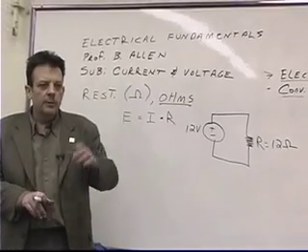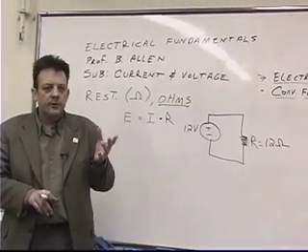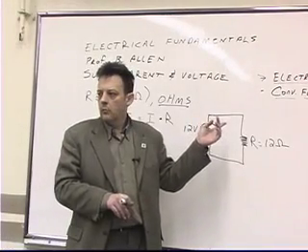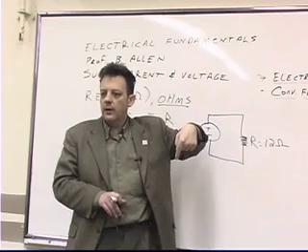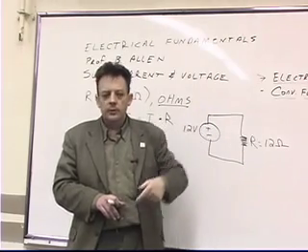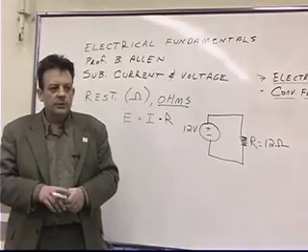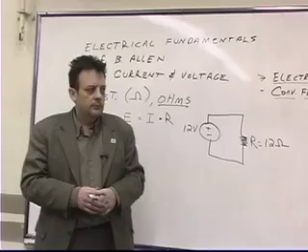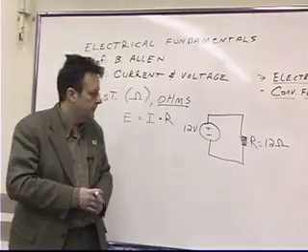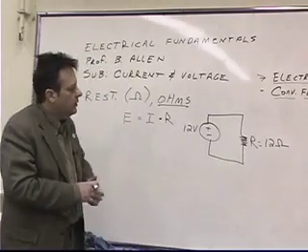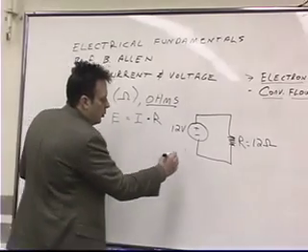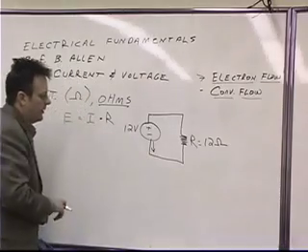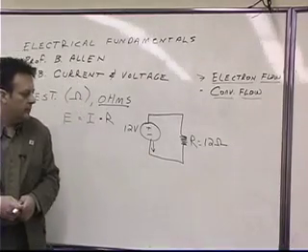With a little bit of math, all they have to say is, yeah, that's a negative current, which changes the direction of the arrow. So it's not that they're wrong, it's just a tradition. It's been handed down for over 100 years. Now, using electron flow theory, we know that the electrons are going to flow out of the negative terminal of the battery.